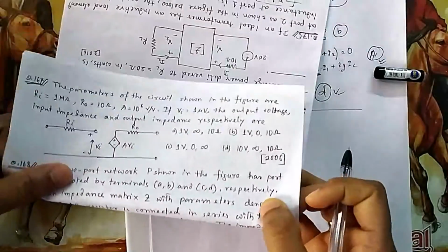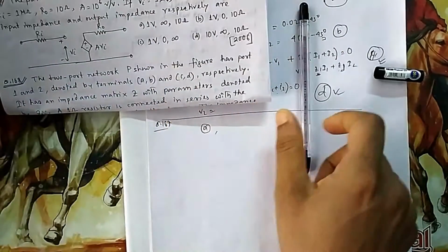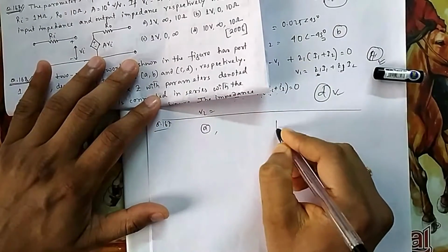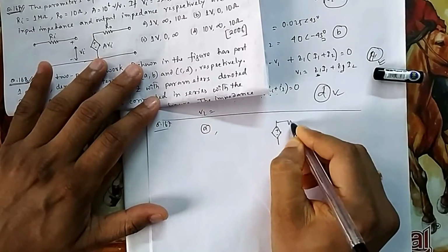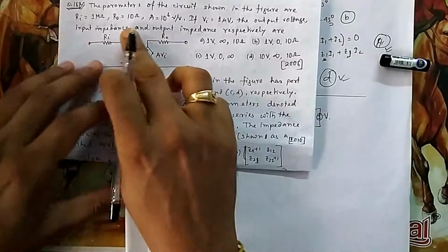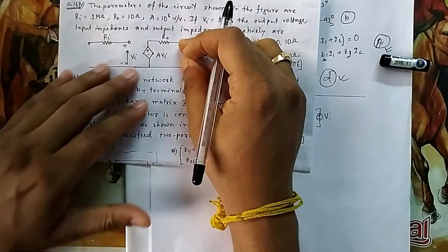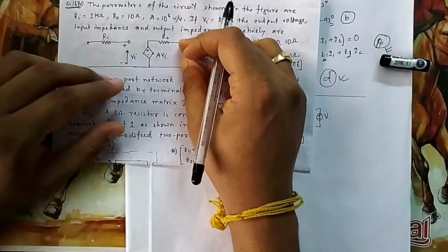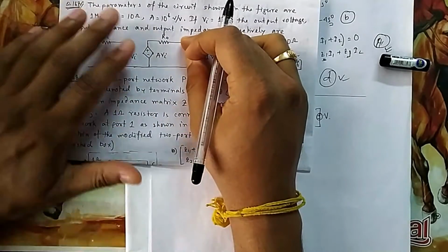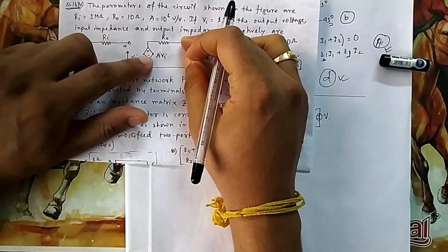But if you want to calculate your output impedance, for that, on the input side also we connected one source. I have not shown it here, but you can think that we have connected one source. So in the output, if we connect another source, suppose of V, my output will look like this. If we want to find input impedance and output impedance, we have to connect a source. If we are connecting a source, that means we are killing all other active voltage sources. That was the idea for calculating Thevenin's in case of dependent sources also. So here also if we connect something, we have to kill all other sources. Here the other source is nothing but Vi, so you have to kill that Vi. So this voltage will be equal to 0.